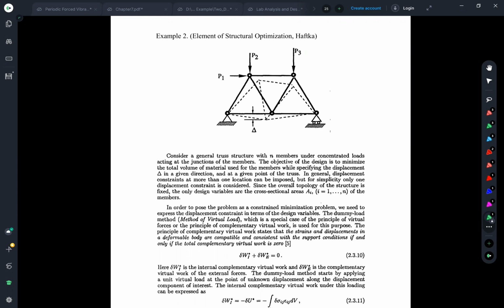The only thing that is different is they don't care about the stresses now, but what they care about is the deflections. If this truss is part of my highway bridge, maybe you're talking about the length out here. If you're using, I don't know, the AASHTO standard, but for the highway, I believe the delta needs to be less than L over something like 800, something like this, right? Maybe it depends on the design code.